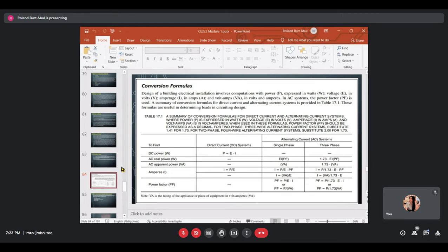This is primarily the result of having several electric induction motors in operation. Some industrial sites will have large banks of capacitors called power factor correction capacitors, specifically for the purpose of correcting the power factor back toward 1 to save on your power company charges. Power factor correction capacitors are not perfect. They only provide a PF close to 1 when the power supply is at near its full rated load.